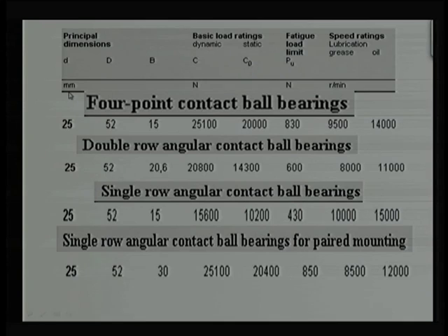And for the same shaft diameter, assuming that this bearing is going to be mounted on a 25 mm diameter, all the bearings are 05 series. That's why it's shown here D 25, 25, 25, 25. Now, the outer dimension, the enveloped final dimension of the outer ring, is also the same, 52, 52, 52 mm.